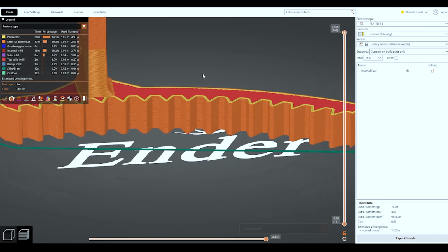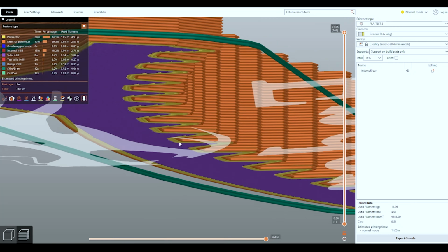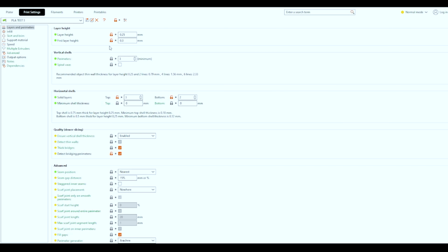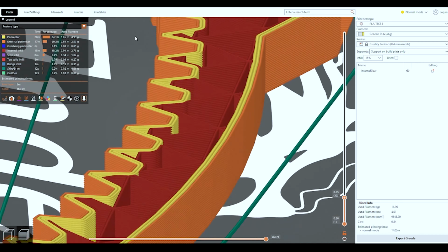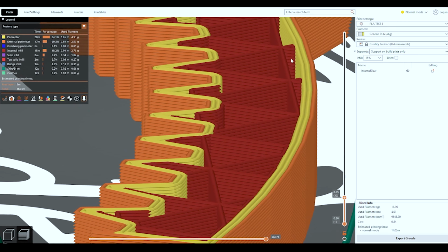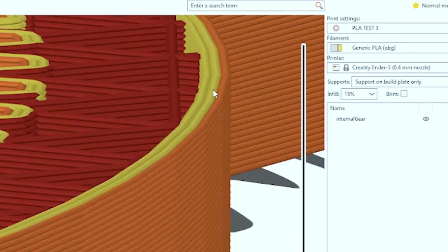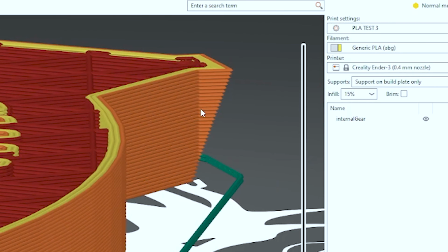Then the layers will be like this. We can see clearly by zooming in. I chose 3 perimeters, which means that we will make 3 walls on the perimeters. This is actually high and gives me a really strong piece, since this piece has a mechanical function.